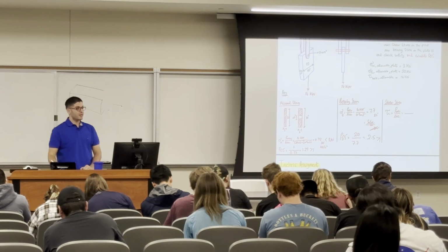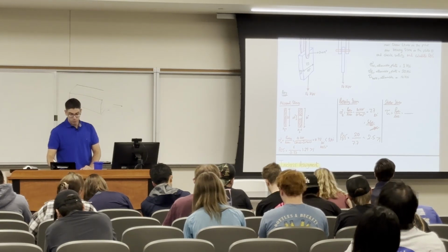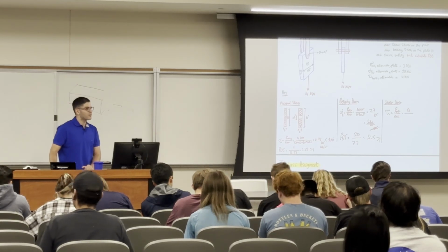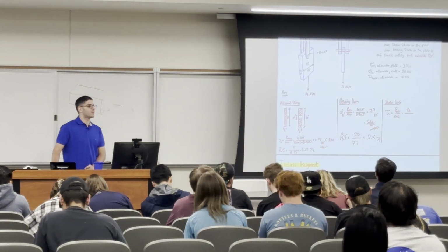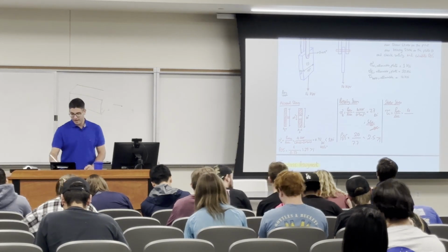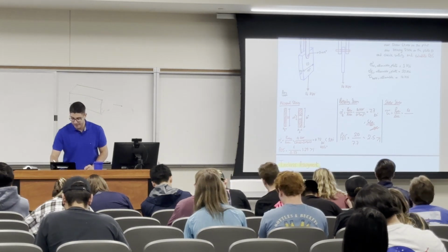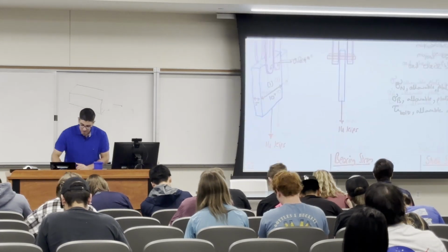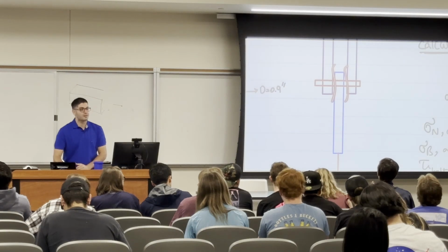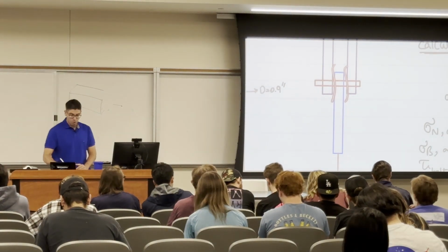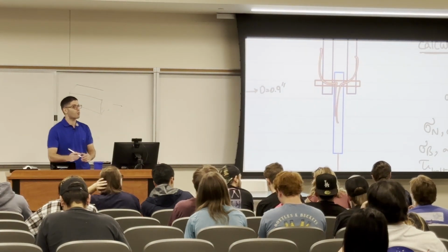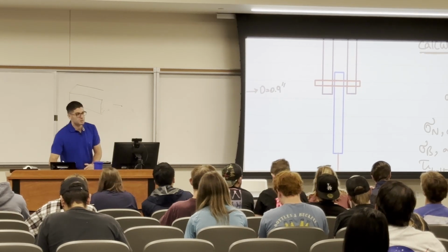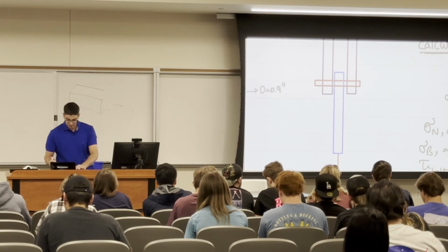What force should I take? 14. Okay, tricky part. Is it single shear or double shear? Double shear. So I either divide the force by 2 or write 2 here as if it's a plane of failure. And whoever said double, the reason is there are 2 chances here that the bolt could fail, or I do have 2 load paths here. That's why I'm dividing the force by 2, because the area of the bolt here is experiencing F over 2.